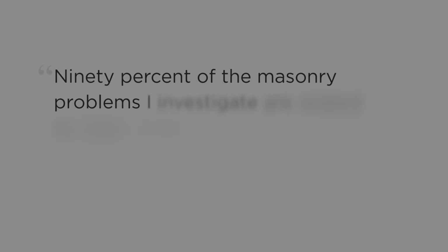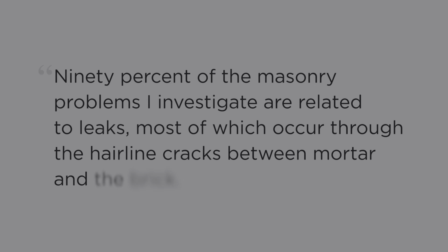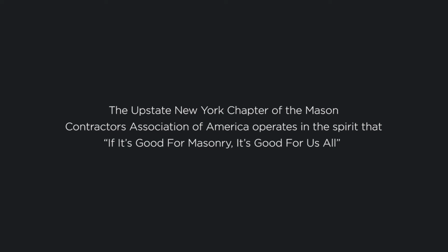90% of masonry problems I investigate are related to leaks, most of which occur through hairline cracks between mortar and the brick. By keeping in mind the building code requirements, you, as a mason, can ensure that job site problems that can stop projects are minimized. Your care and knowledge will ensure that masonry will continue to be the premier building system in our community.